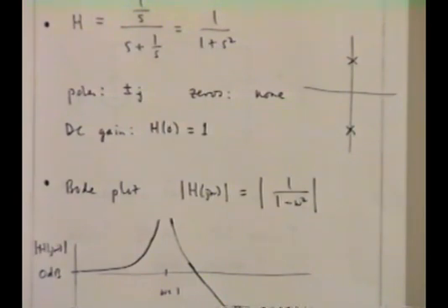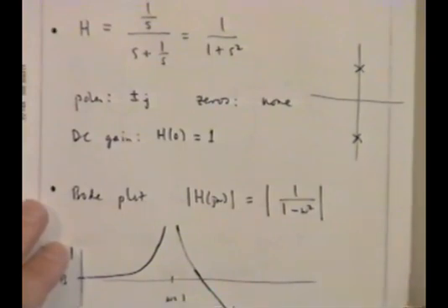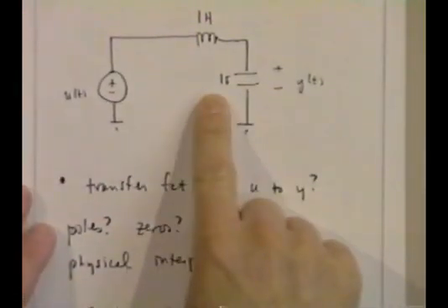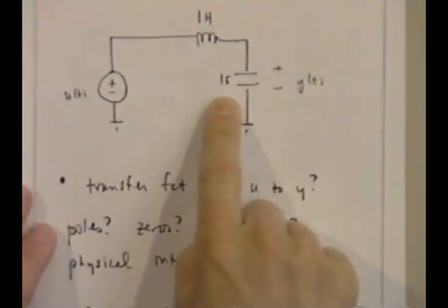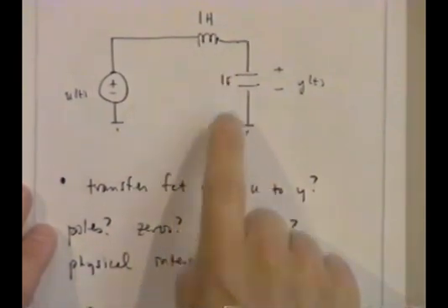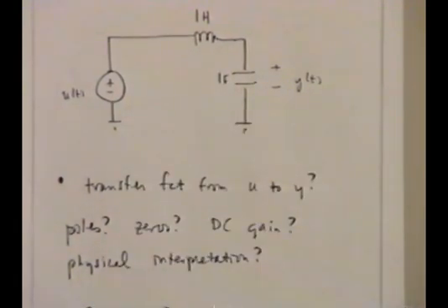Yeah, what would the poles then be for 1 over 1 minus s squared? Plus minus 1. And what do you think of immediately without further provocation? You think of the nature of the solution: there's a decaying component and a growing component. If you thought of a decaying and a growing component and you saw this circuit, you should be profoundly suspicious.